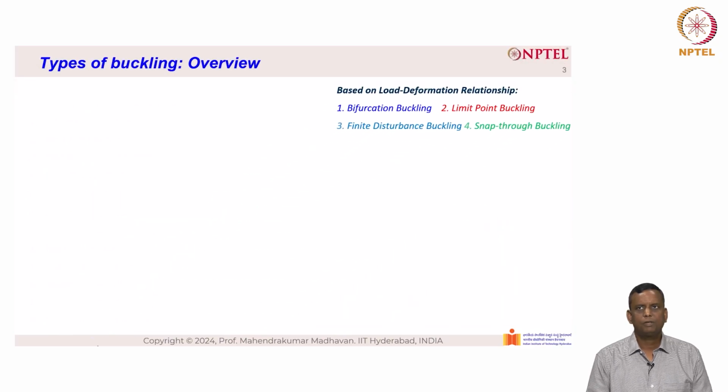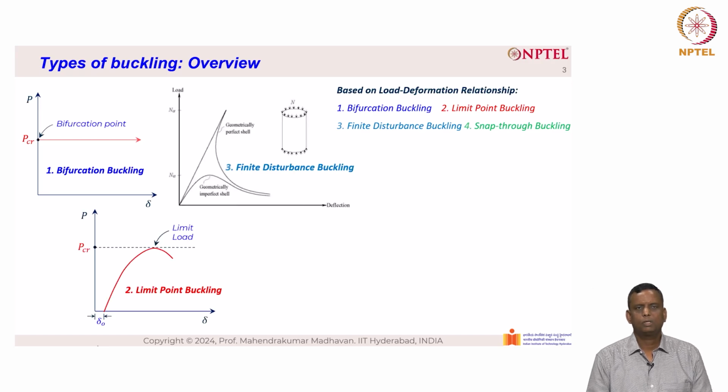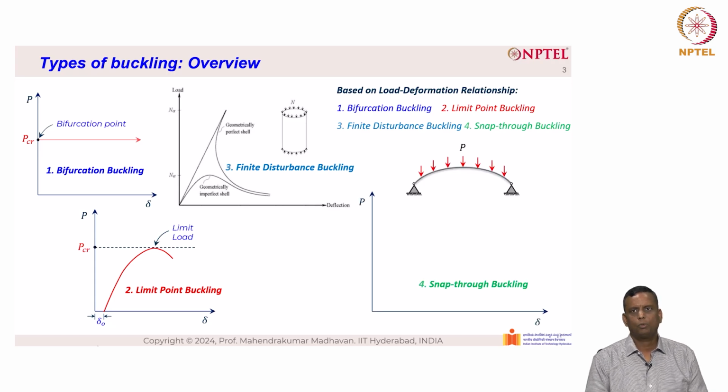So based on load deformation relationship, the first figure introduces bifurcation buckling, the second one is limit point buckling, the third one is finite disturbance buckling, and the fourth one is snap-through buckling for shallow arches.